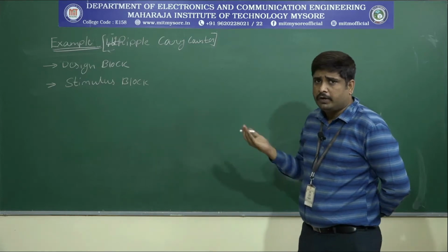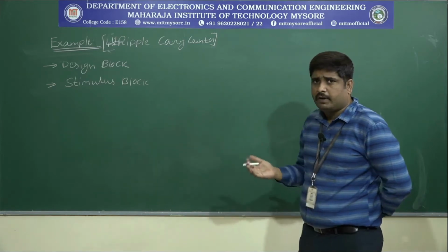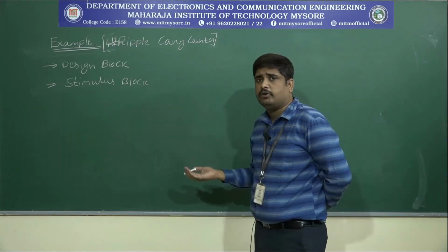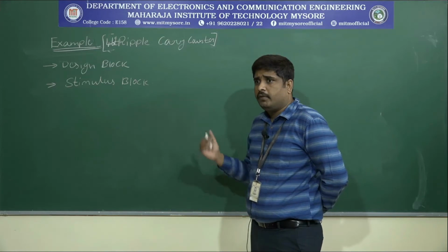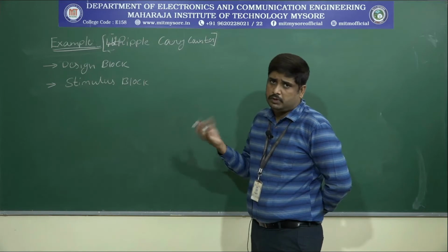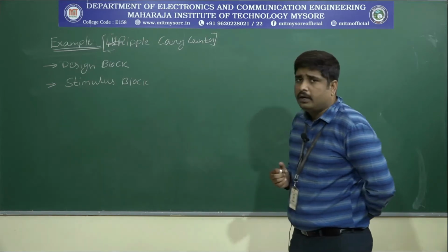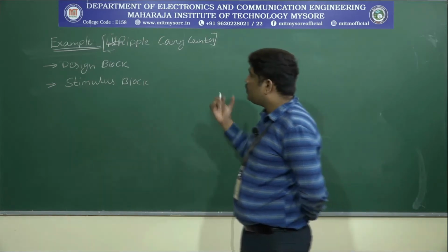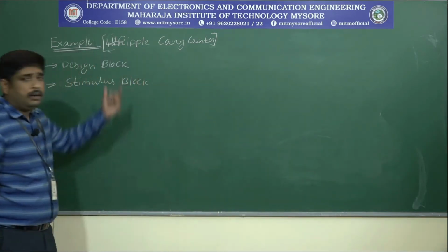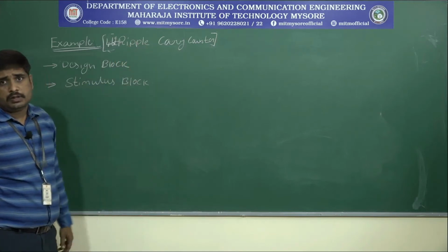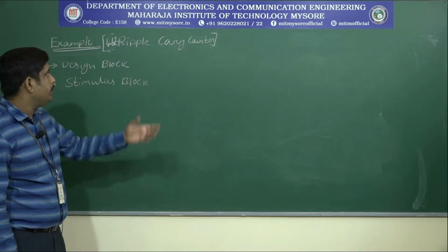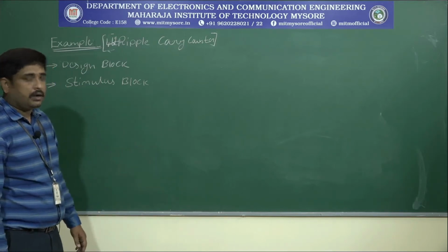Usually we are going to use a T flip-flop. Why T flip-flop? Because it's faster than other flip-flops. When you apply T equal to 0, at that time there is no change. When you apply T equal to 1, then it continuously toggles. So it's very suitable for 4-bit ripple carry counters. A 1-bit counter requires 1 flip-flop, so for a 4-bit ripple counter, 4 flip-flops are required. Just connect all the 4 flip-flops, then it becomes a 4-bit ripple carry counter. So let us